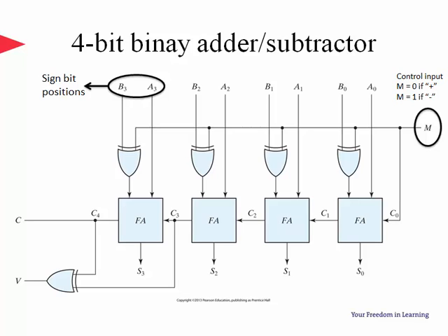If both are negative, to generate an overflow C3 must be 0 due to negative numbers being represented in 2's complement form. Then, since the sign bits are 1 in signed arithmetic, the output carry C4 shall be 1 and hence V is 1, meaning that there is an overflow detected.